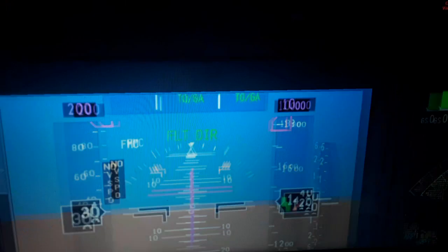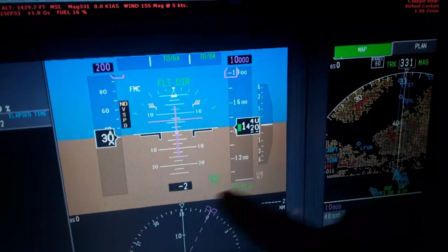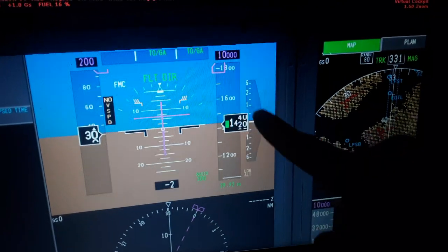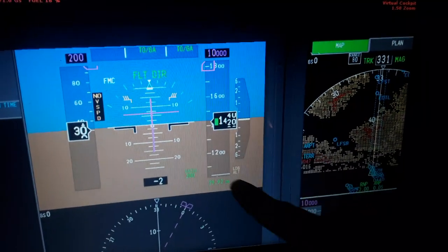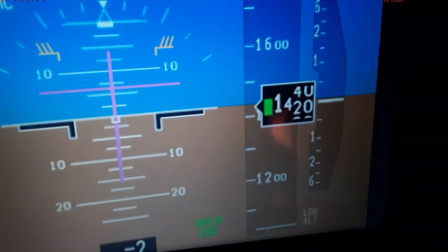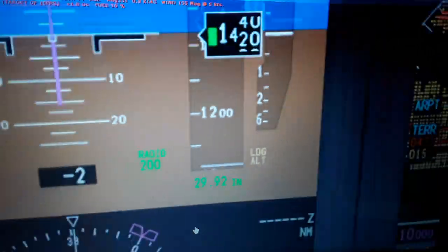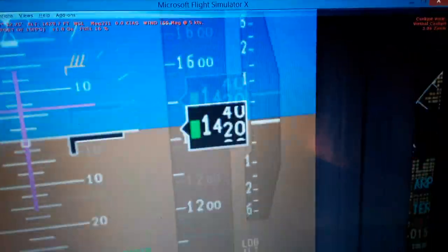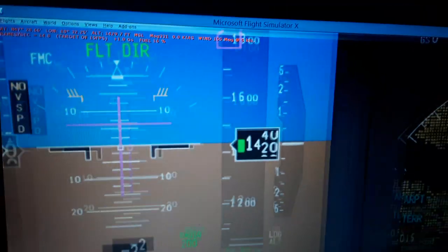You can see the airspeed indicated, the airspeed tape over here is gonna increase when we're gonna be flying. The altitude above the ground, the barometric altitude above the sea level, 1432 feet. For this barometric pressure setting, 29.92 inches of mercury. Radio minimums. You can see this needle here moves up when we climb and down when we descend, it turns hundreds and thousands of feet per minute.